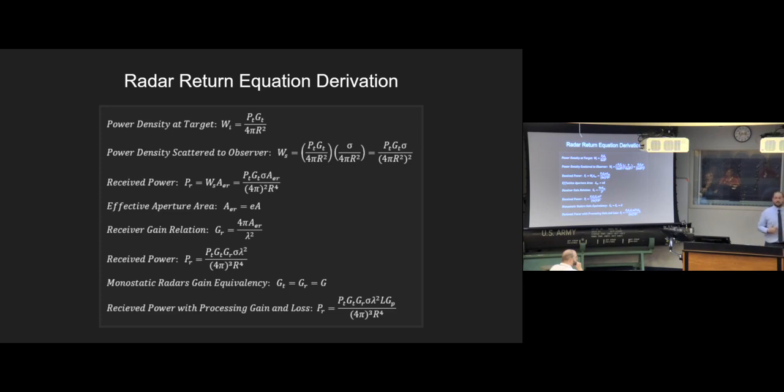But we have sensitive antennas. We can detect it. But to be useful for signal processing, we need to boost it. That's all this is, the receiver gain. But again, it's the gain of the antenna, which is complicated again. Just think of it as a scalar value, no unit, just a multiplicative factor. But as you can see, it's a relationship between that effective area, that aperture, and this is wavelength.